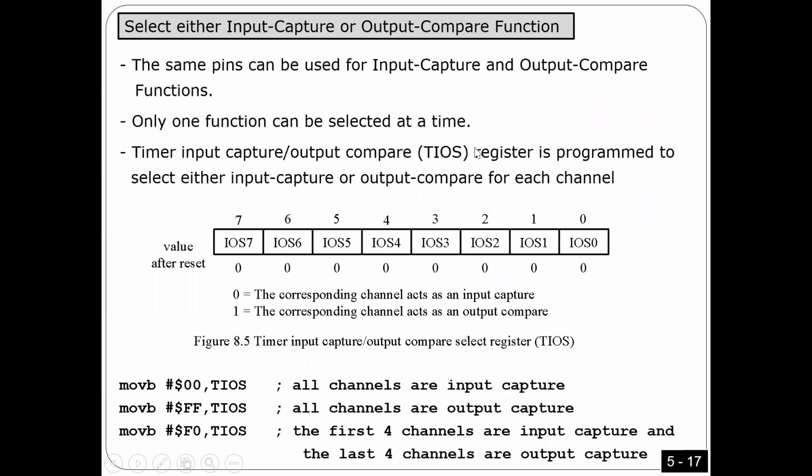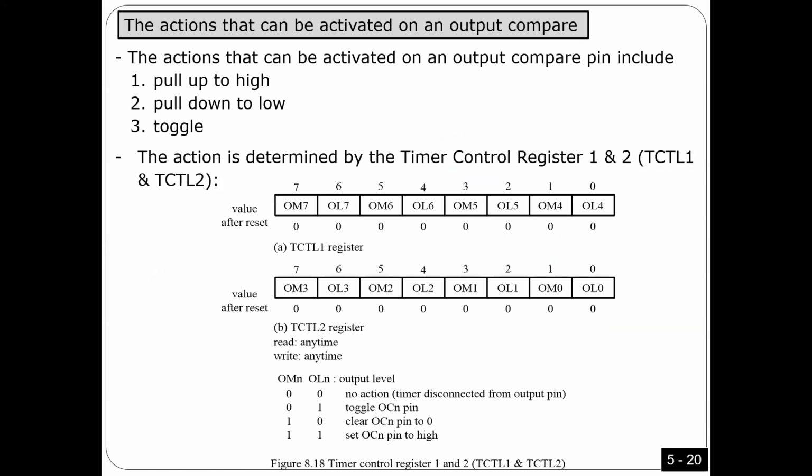So look here, guys. For example, in case of TIOS, if I want channel 0, I'm gonna put 1 here, right? If in the exam I tell you channel 4, then the 1 should be here. That's it. It's exactly the same thing, you just change the configuration. Very simple. Anyway, that's all I need from this chapter. Only these 2 programs. Again, how can you use input capture as IRQ, in C and assembly? How can you use output compare like RTI?